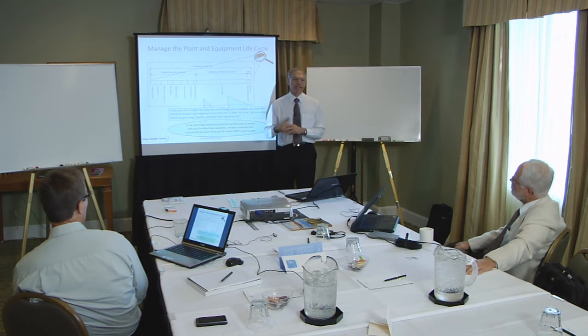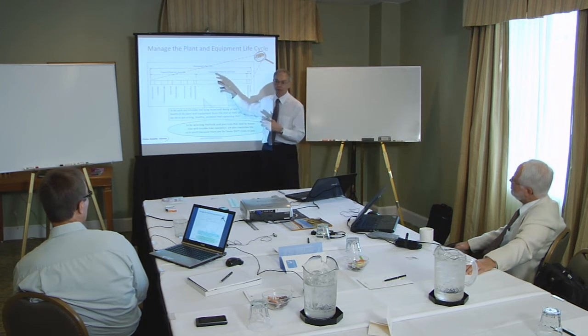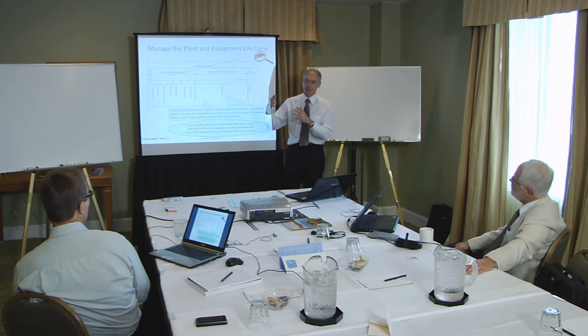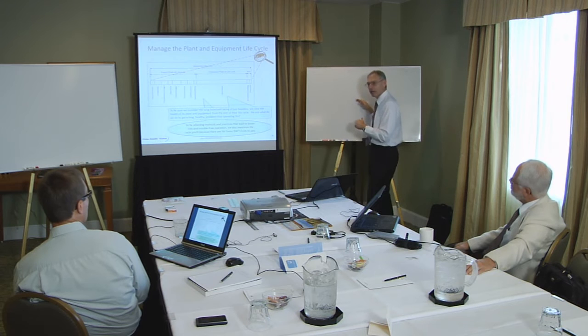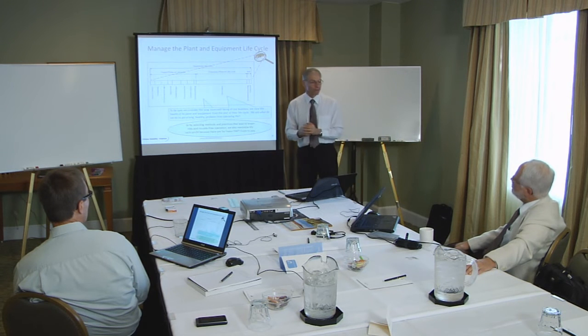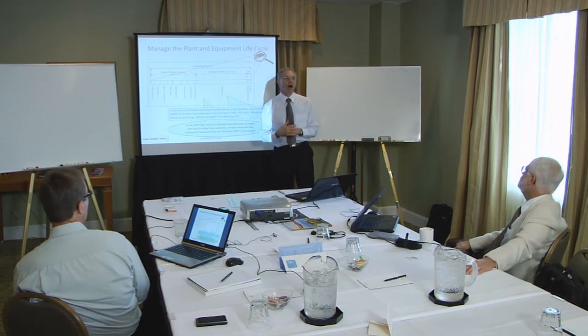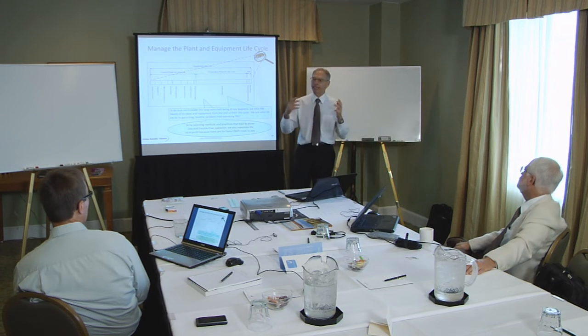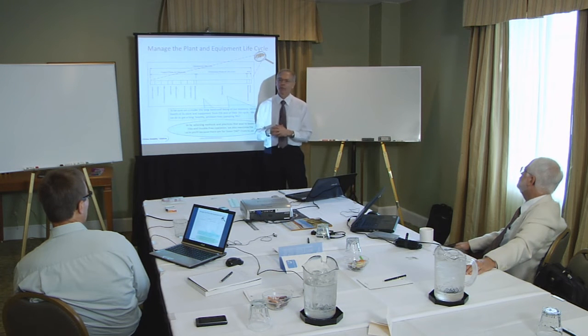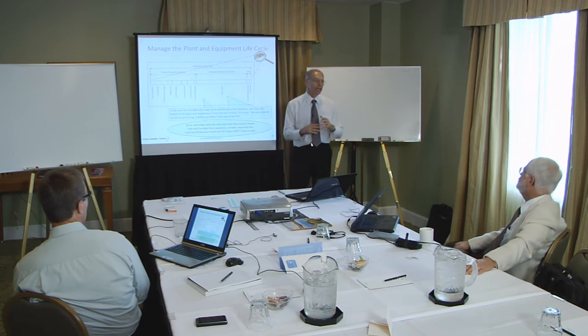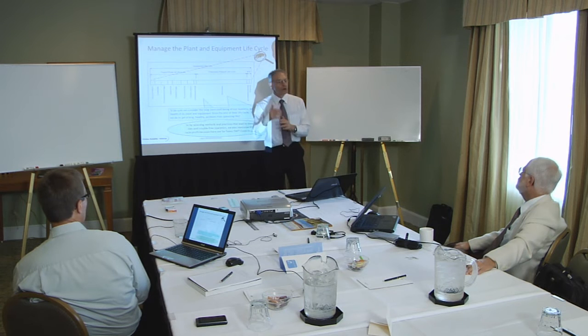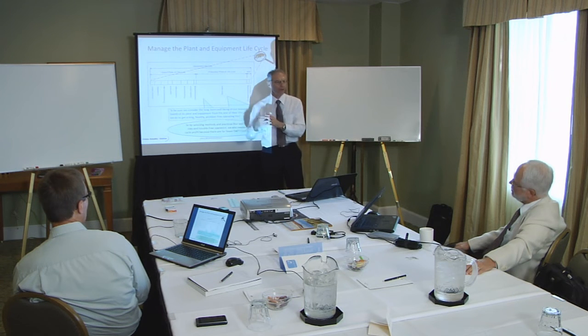With aircraft, they tend to count the number of stresses, so they know how much life is lost out of the parts, because they actually monitor that stress level and realise that the degradation is happening. If there's been a low stress life, if the machine's been looked after well, it's got plenty more hours left. But if it's been flying through some nasty environments and badly treated, then they know that life is just not there. It's been taken away by the harsh life it's lived. So yeah, we can massage, we can try and work with and replace parts and extend the life, but eventually it's going to come to an end.